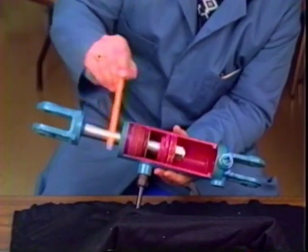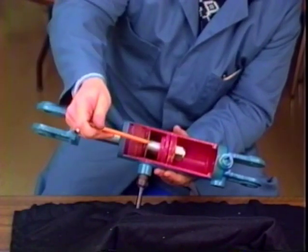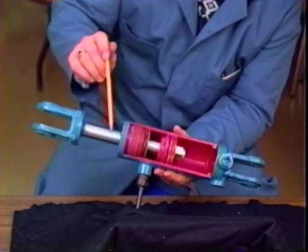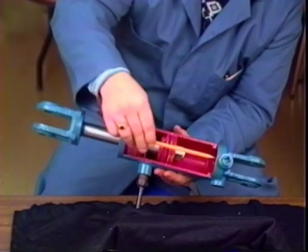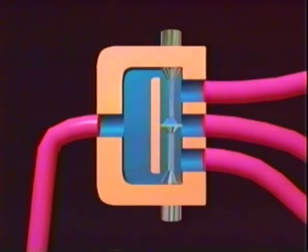The cylinder converts fluid pressure into linear motion. By diverting hydraulic fluid into the upper and lower chambers of the cylinder, the operator can move the piston and the attached piston rod up and down. The component used to direct the fluid is the control valve. The valve shown in this simplified graphic is an open center valve. It has 3 operating positions.